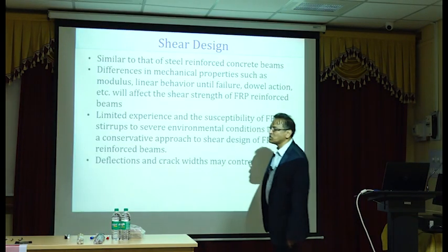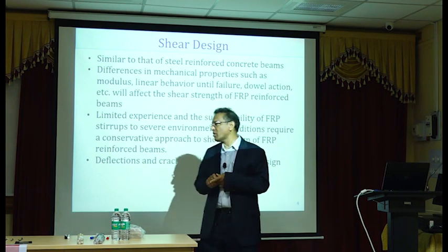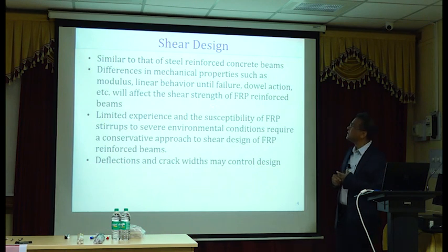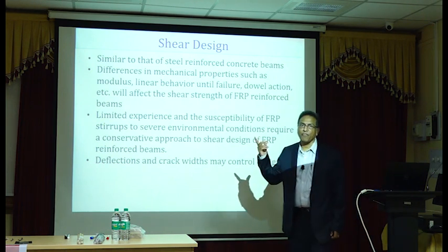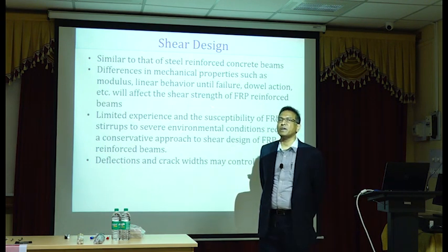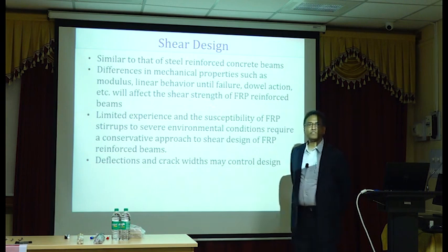Okay, today's topics are two topics. One is shear design and the other one is bond strength, or development strength, or development length. So shear design for FRP bar reinforced concrete beams is almost similar. It's not the same, but similar to steel reinforced concrete beams.